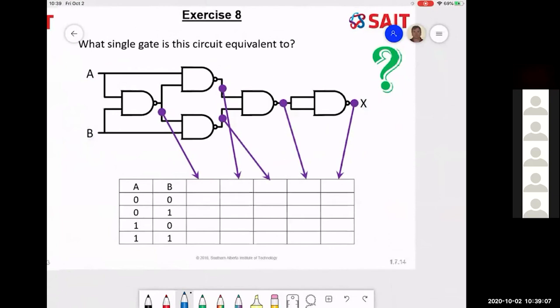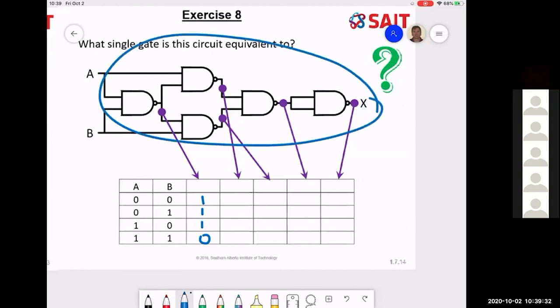Well, if I look at A B, if A B is 0, 0, that would be a 0, inverted would be a 1. Etc., etc. If I go through and solve this, you're going to find out that it is equivalent to one of the gates we've discussed today. This is real world. This is really how we build that gate. Even though it looks on paper to be a lot more complex, it is cheap, it is fast, and I can make them with very high quality with very little effort this way.